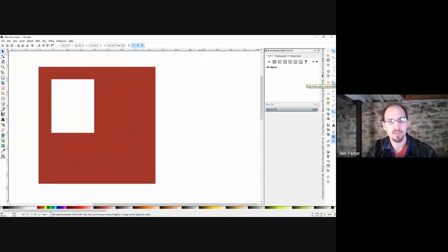First off, you want this toggled, snap paths, nodes, and handles. And generally speaking, you want that toggled, like as a standard. If I draw and I have these two toggled, I could just draw like that.